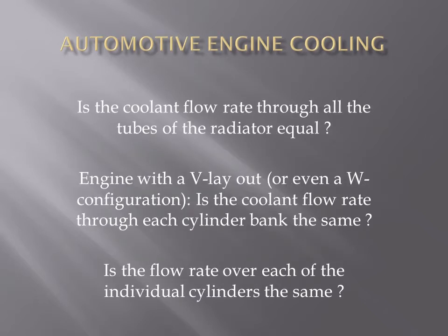Is the coolant flow rate through all tubes of the radiator equal? Engines with a V layout, or even a W configuration: is the coolant flow rate through each engine bank the same? Here you will once again find that the one with the poorest coolant flow has the largest temperature difference over it. A very undesirable situation. Third question, is the flow rate over each of the engines?